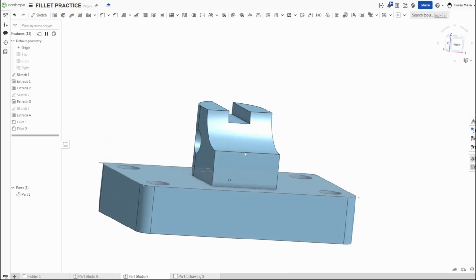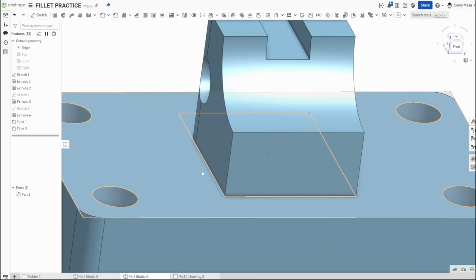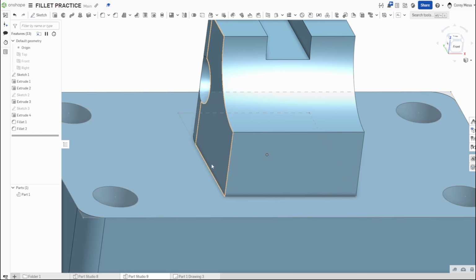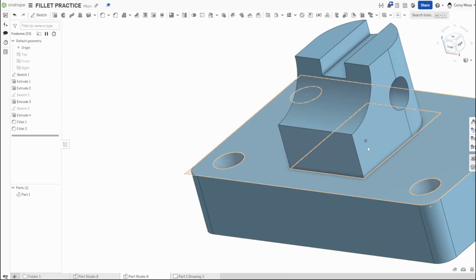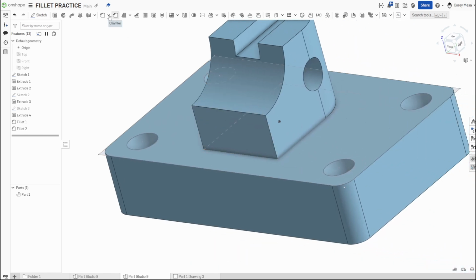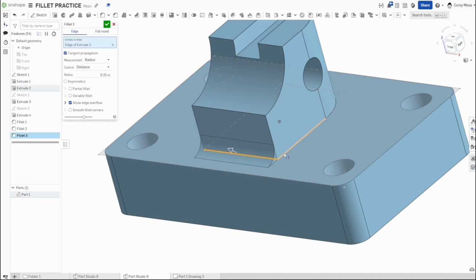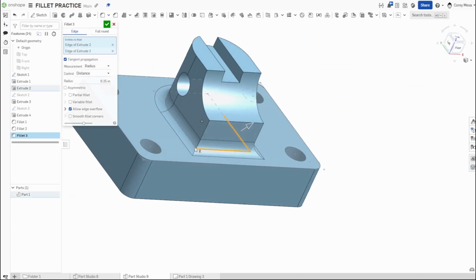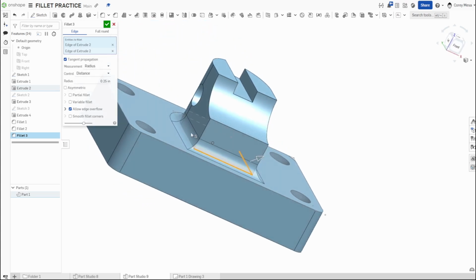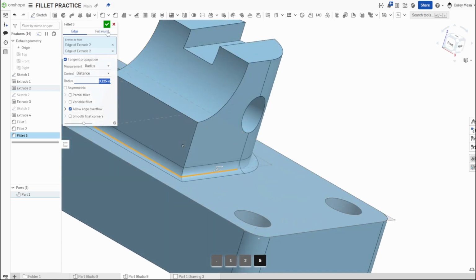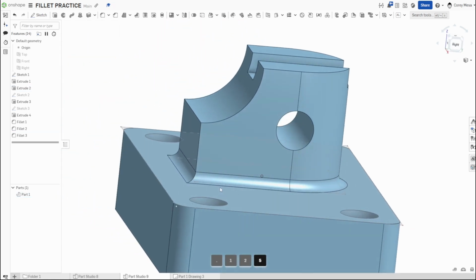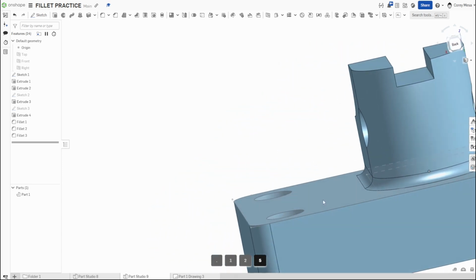I talked about using things for 3D printers. For me personally, I might want to be showing how this is going to get welded to something. Maybe this top part is one piece and the bottom plate is another, and it's going to be welded to it, maybe in some sort of fixture. Let's do a fillet, and I can click all the way around, and you'll see it's going to give me, maybe it's only a little bit of a shallow weld. So we'll say okay, 0.125, and you'll see I get a nice rounded edge up to here.